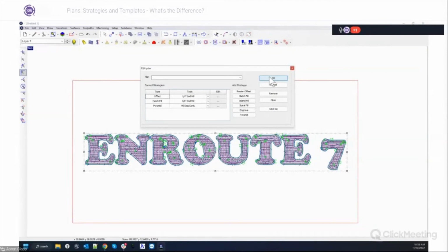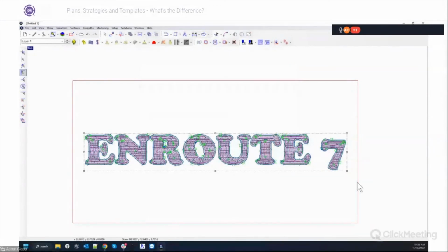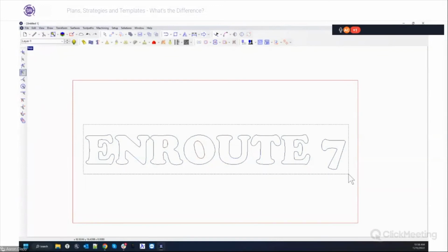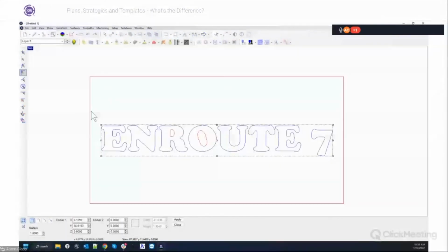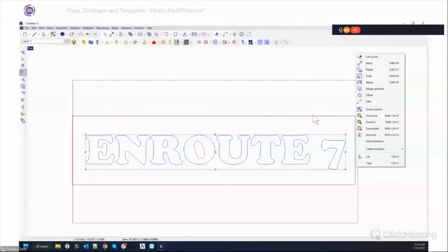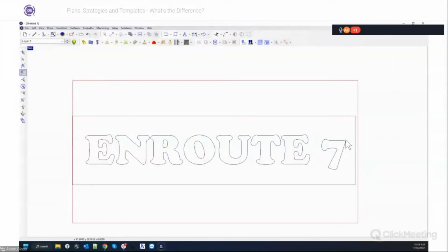Yeah, you definitely could. Again, it's one of those things where if it's all one geometry, yes. Although I would say that typically push-through letters have two sets of geometry with one single toolpath. So for example, let's delete the toolpaths off of here. Let's just say we put a rectangle around this. Okay, so this would be your face board, right? So this would be the piece of material, like brushed aluminum or whatever it is that you're pushing the letters through. This is your face material, right?